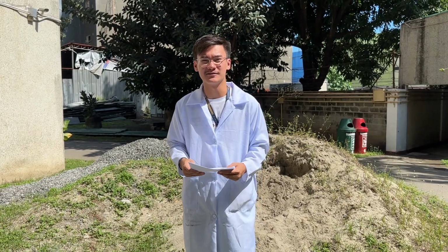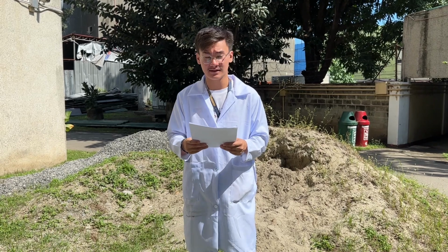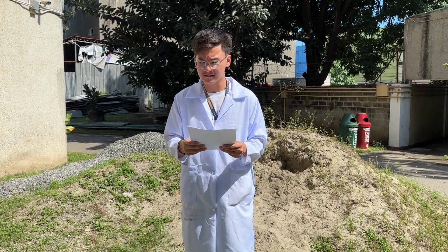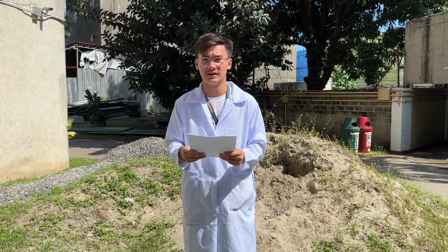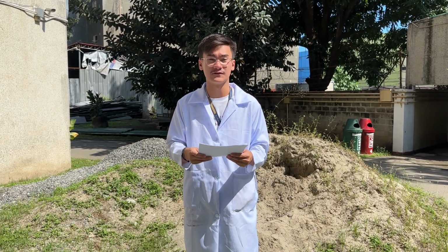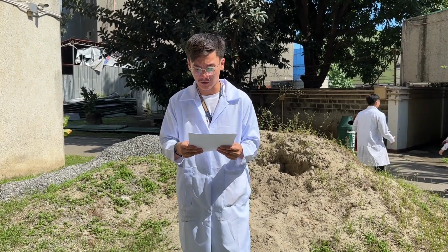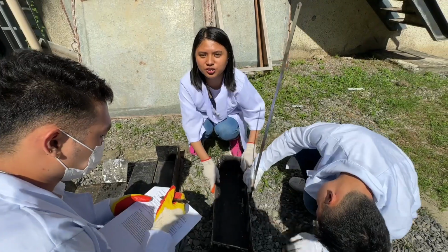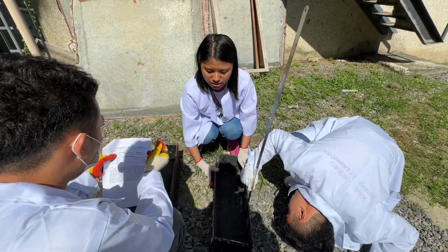So for our experiment, we're going to use the following materials. First is the Portland cement, sand fine aggregate, gravel or coarse aggregate, and oil for the beam mold. And for our equipment, we're going to use the following: beam mold, tamping rod, mallet, shovel, trowel, slump cone, and mixing pan. Okay, so now we're going to measure the dimension of each beam mold by its length, width, and